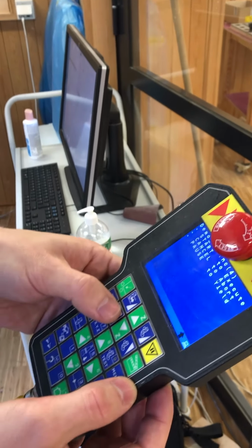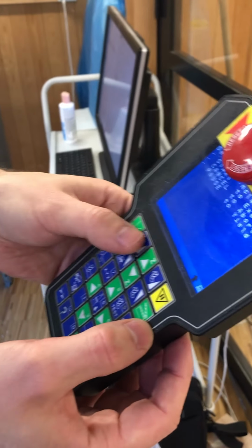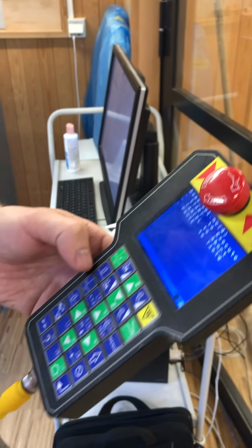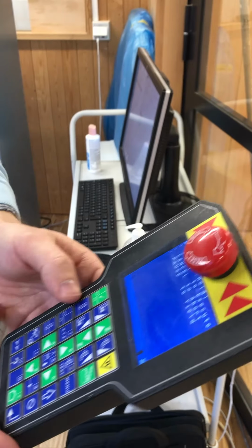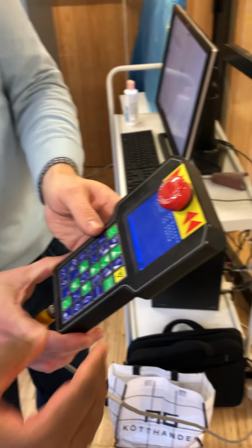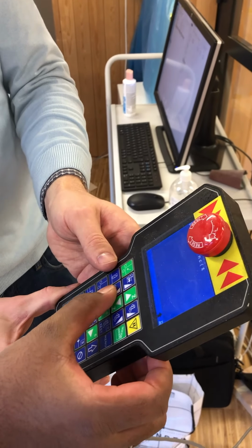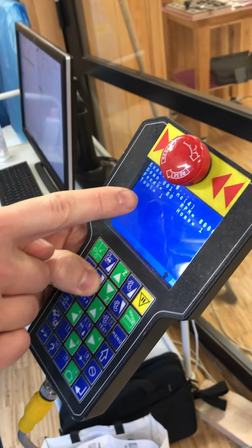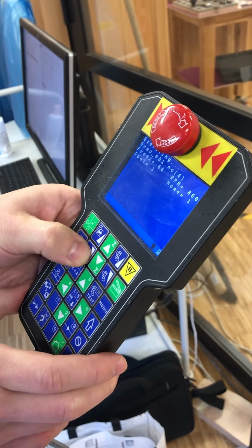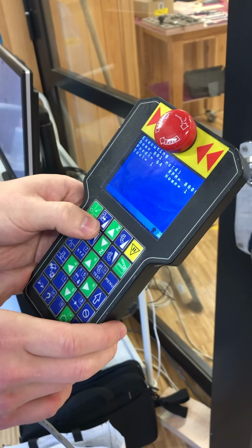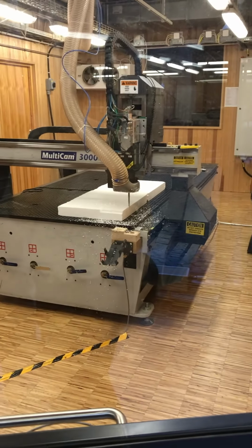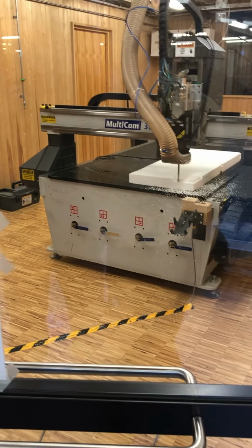And the first thing we'll do after pressing once again on execute to start the operation is to reduce the feed rates. And now we reduce it to 60%. So Arif, do you want to press the execute button? Yeah, I can do it. And then now I just hold down, so it's 80%, 50, 70, 60, and now 68, 65. It's fast. Yeah, so now it's more than 64%.